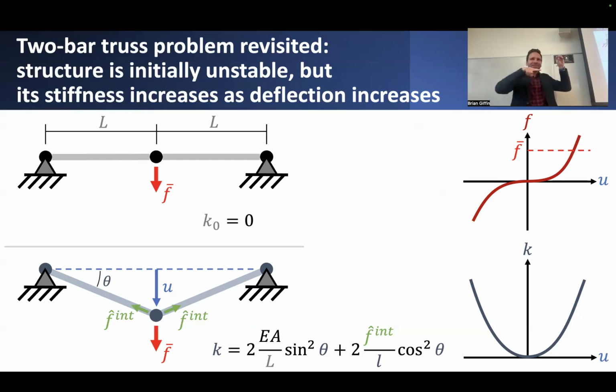Well, the cable overall is going to deflect downward, it's going to sag, and it's going to stretch out a little bit. Certainly, you can think of the overall length of this cable, if it was equal to 2L, as shown in this case. If it starts deflecting downward, and if that deflection is significant enough, then the overall length of this deformed cable in its sagged configuration is such that it has elongated somewhat. And you would expect that that should contribute to some increasing resistance to that transverse load. And that's exactly what happens. And that's precisely what our nonlinear relationships between strain and displacement tell us.